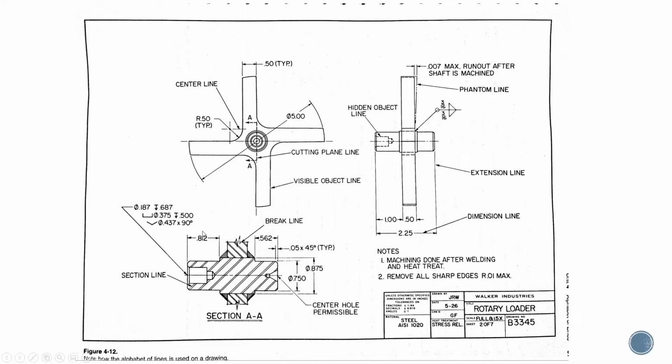Some of the other features you see going on in here are these arms that would be coming off. If we bisected this along here, we can see that these arms are the same steel, but they're in a different orientation to this centerpiece. That lets us know that these arms are actually separate pieces that are then welded on.